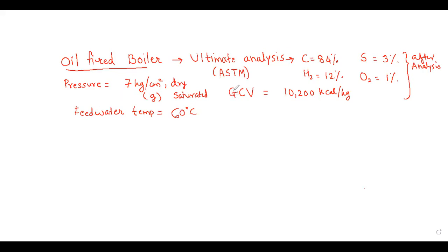And then you also need to note down the flue gas, combustion gases temperature. That is, the products of combustion gases temperature is also recorded using thermocouple. As an auditor you have recorded it as, let us say, 220 degree centigrade. So the gases which are leaving the boiler are at 220 degree centigrade. Surrounding temperature also you must note. Surrounding temperature is, let us say, 27 degrees centigrade, which is recorded again by the auditor.